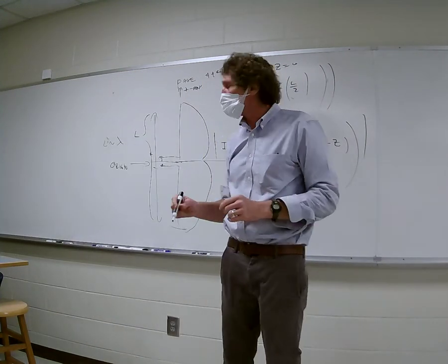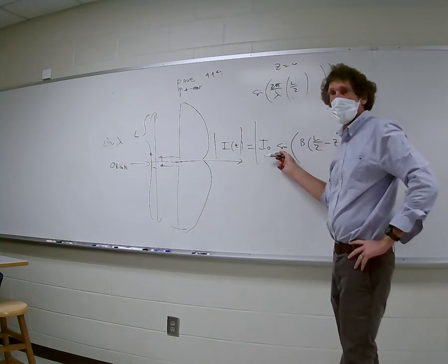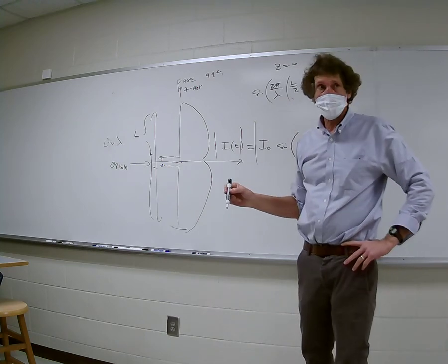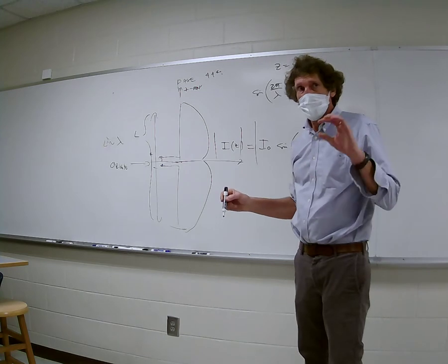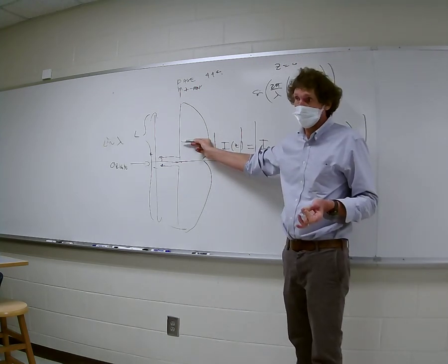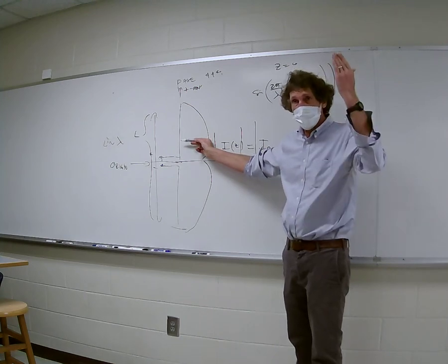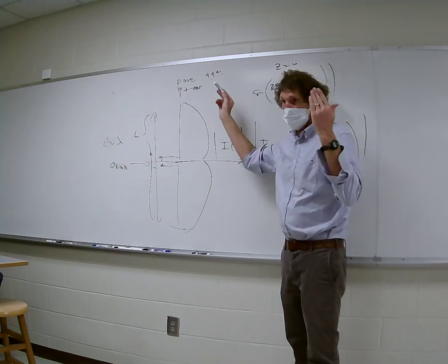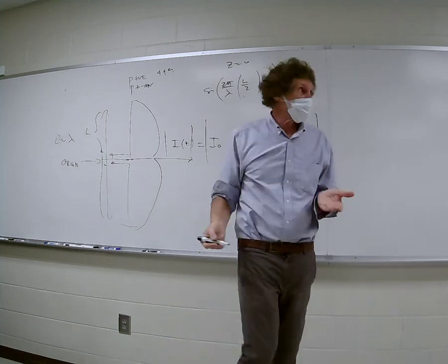So if we have an arbitrarily long antenna, and this is the current distribution, then the logical question is how would you calculate the electric fields from it? Y'all agree? And here's the way we always do it. I call it the building block approach. We find the electric field from a little chunk of current anywhere on that antenna, in the far field. And then we integrate that field value over the length of the antenna, and that's basically the total. This is the building block approach.